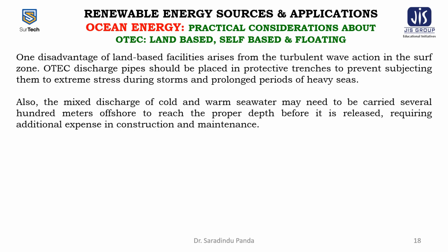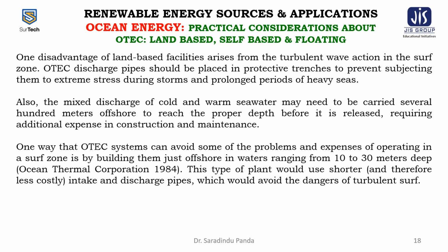Also, the mixed discharge of the cold and warm seawater may need to be carried several hundred meters offshore to reach the proper depth before it is released, requiring additional expense in construction and maintenance. One way that OTEC systems can avoid some of the problems and expenses of operating in a surf zone is by building them just offshore in waters ranging from 10 to 30 meters deep.